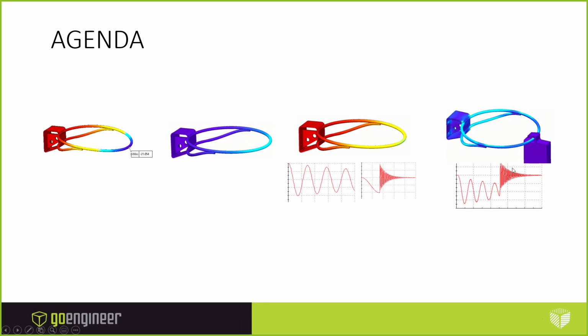Basically, what I'd like to solve for in this analysis is, first of all, the natural frequencies. I'd like to figure out what the natural frequencies of this structure are. Does it vibrate at 3 hertz, 20 hertz, 50 hertz? And also displacements. Ultimately, I'd like to estimate the displacement, and that leads to stresses and so on. But to keep the presentation short and concise, I'm going to mostly focus on the natural frequency results, and those are the ones we'll be comparing. If you have questions on how we might estimate displacements later on, let me know, and I can address that.